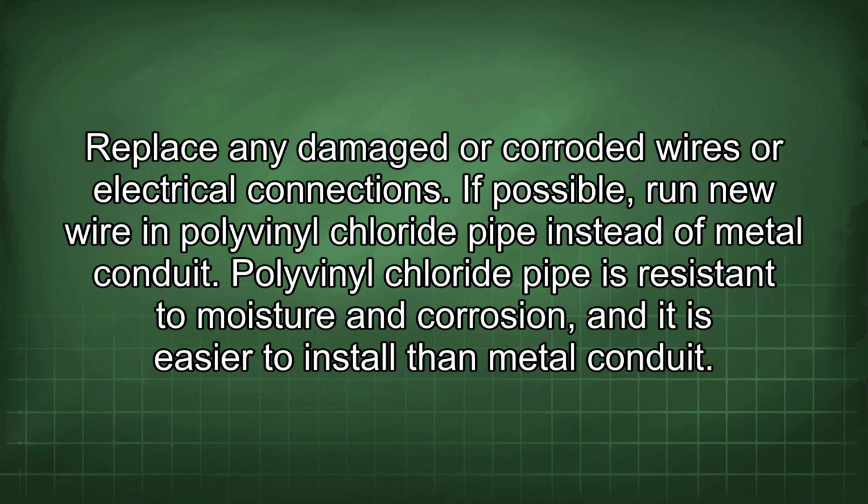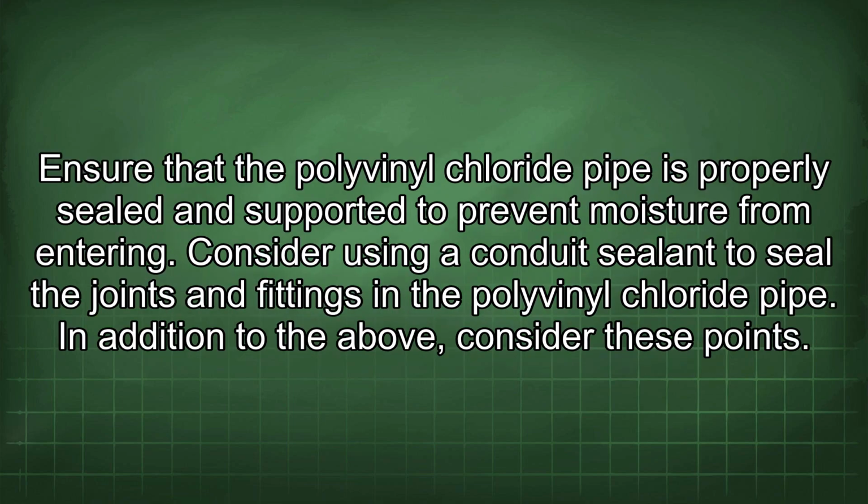Polyvinyl chloride pipe is resistant to moisture and corrosion, and it is easier to install than metal conduit. Ensure that the polyvinyl chloride pipe is properly sealed and supported to prevent moisture from entering. Consider using a conduit sealant to seal the joints and fittings in the polyvinyl chloride pipe.